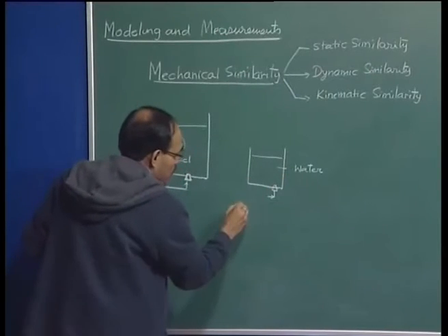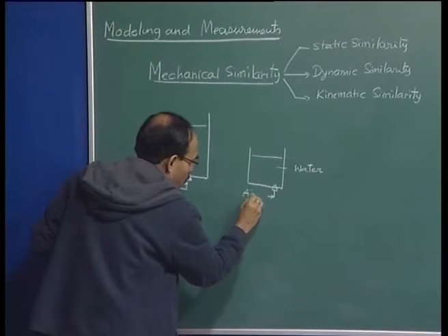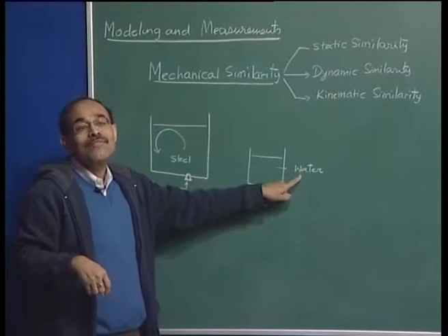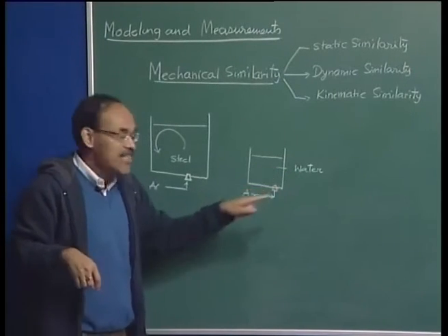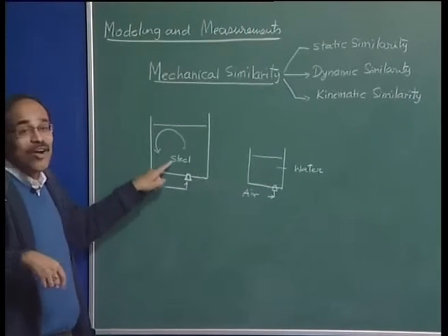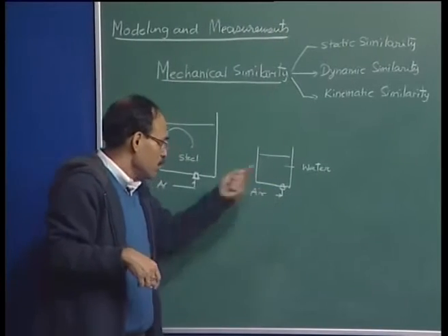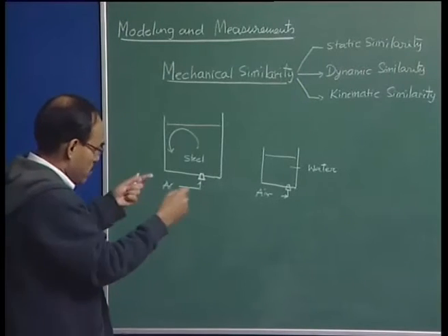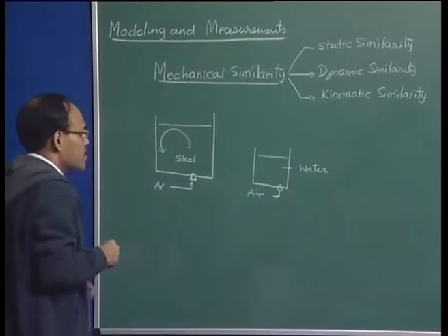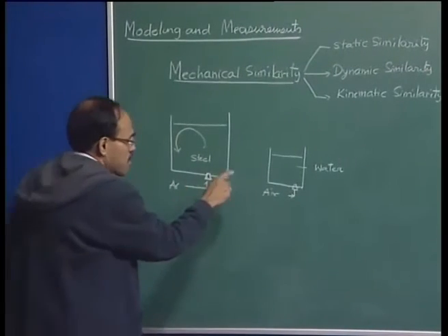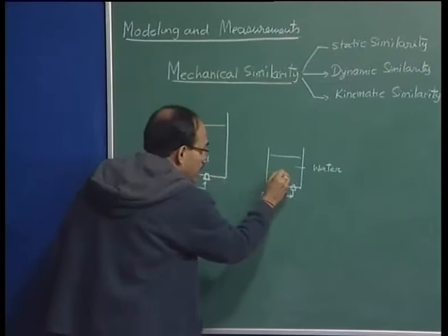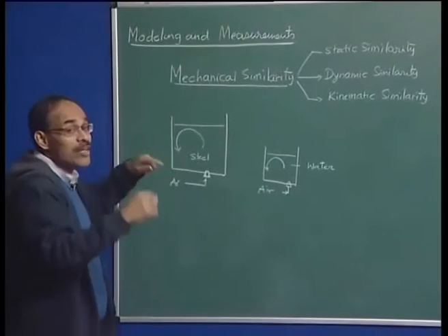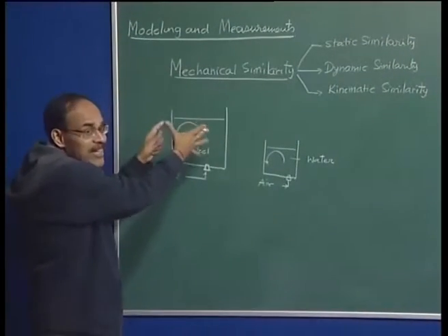So, we inject air, for example. We cannot use possibly carbon dioxide, because carbon dioxide will dissolve in water. So it is going to be a reacting system. This is an inert system, argon does not dissolve in steel. The air also, if the water is assumed to be saturated, does not dissolve, nitrogen and oxygen not too much. So, we can assume that this constitutes an inert system. Now, this system and this system, or the flow of water in this, the flow is going to be the systems. When we talk of systems, it is the molten steel contained in the ladle that is now the system.